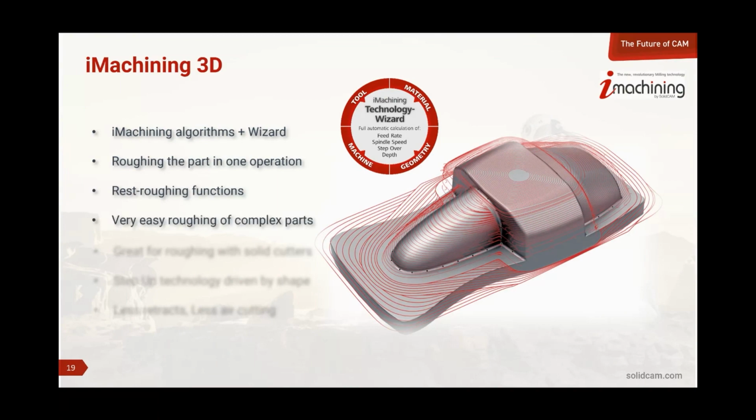It also makes it extremely easy to rough out very complex parts, things that if we had to set up constraint boundaries might be very complex to figure out where to set them. With iMachining 3D, the system takes care of that for you. This is great for roughing with solid cutters. Many people don't realize it's also very good for roughing with inserted cutters, and we'll talk about that in a little bit as well. We use what we call step-up technology driven by the shape.